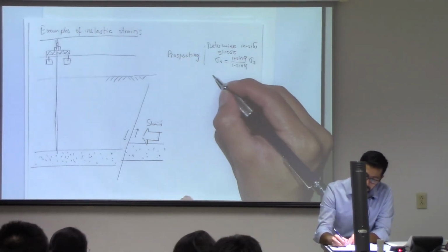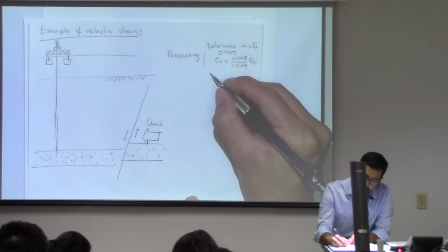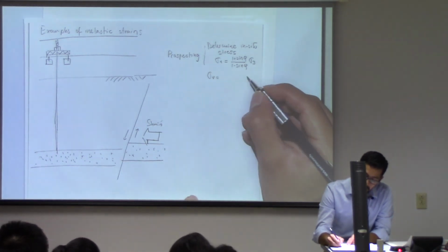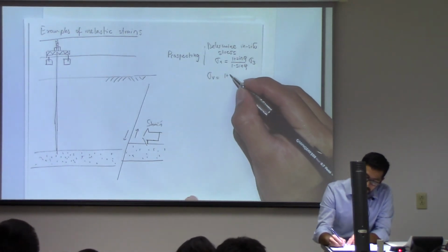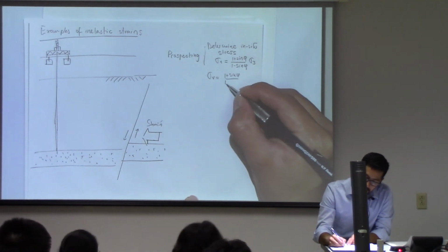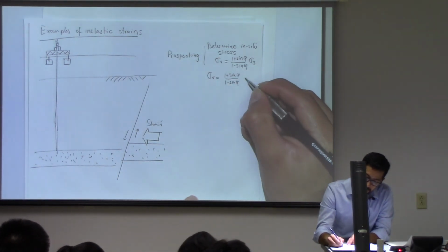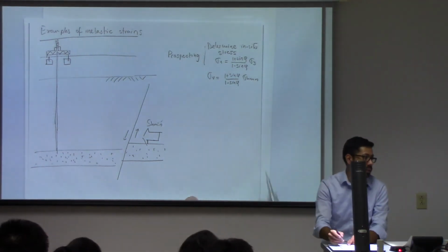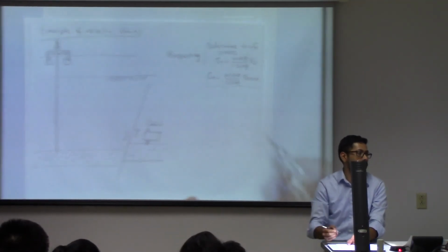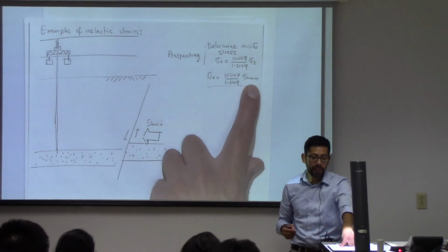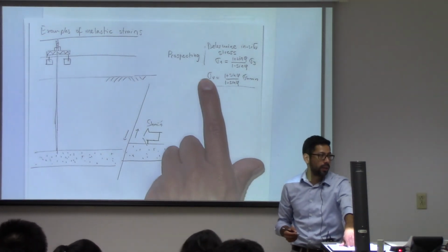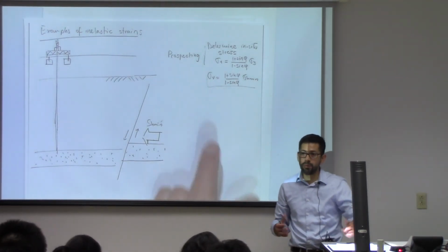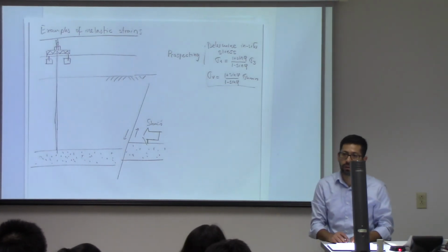According to this equation, the minimum principal stress depends on the effective vertical stress according to that relationship. This one cannot be any lower than this value divided by that one, because otherwise it will fail. It will be a failure.